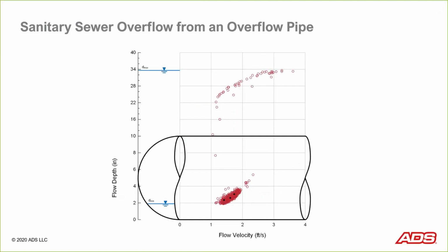So here's an example of a 10-inch diameter sewer. You see the data here, and we are going to plot the Manning equation on this scattergraph. And that denotes three regions that you have in this data. You have uniform flow, backwater, and surcharge conditions. But you'll notice the surcharge conditions look a bit different than they did in the previous example.